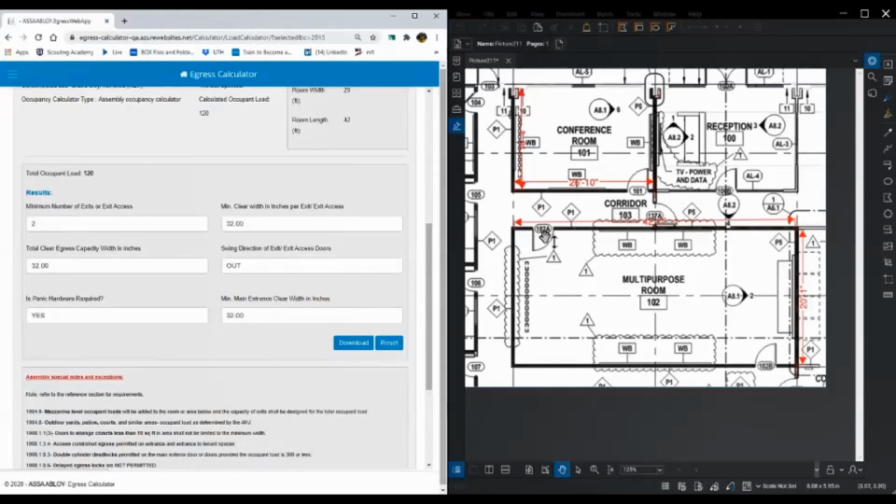The problem now exists when you swing this door out. If this is an egress corridor, now we have to pay attention to encroachment, which means that during this swing, this door cannot cut down more than half the required width of this corridor. It can bring up other issues. You can't really quite see it, but there is another door right here. We may need to have the architect pocket or recess these doors instead of having them swing onto the corridor. They can swing out, but up against a wall or something like that.